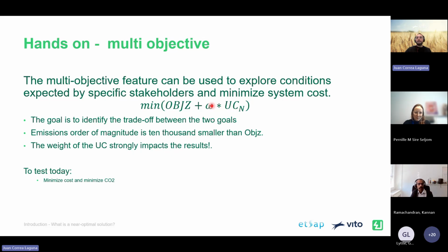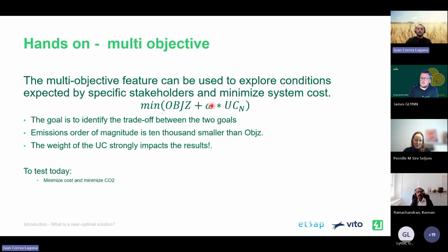And then you have a different user constraint that is similar to what PIPES is doing. So they have a weight that is basically from the run of the model, and they defined a weight that is how much installed capacity was used out of the maximum potential. They use that weight to build a user constraint that has all of the capacities of all of the regions that you are using in that model, and then you minimize the dependency. So basically, it will try to deviate from that region where you have a lot of dependency.